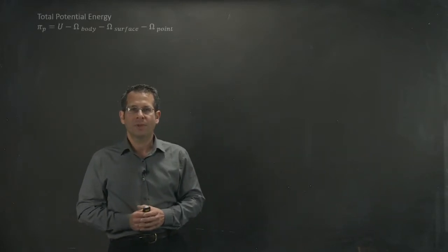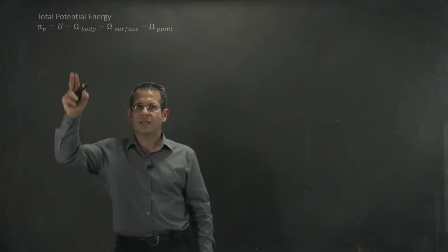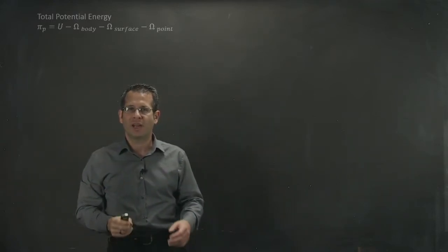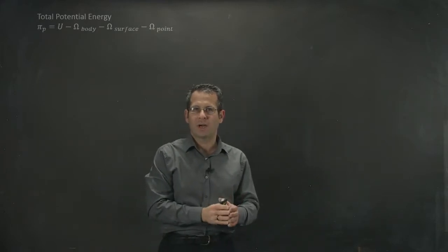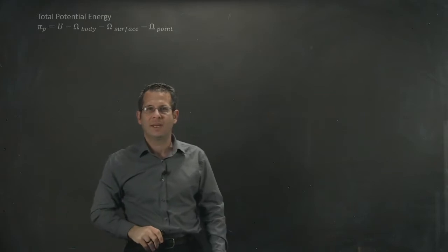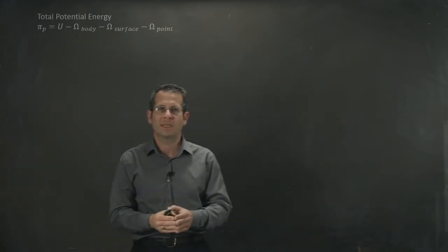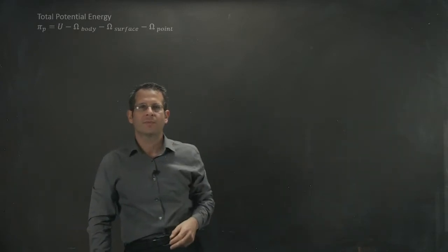Remember, our total potential energy stored in our system or in our element is the total potential energy due to the strain energy stored in the system minus subtracting off the work that has been done by body forces, by surface forces, and point forces applied at the nodes.